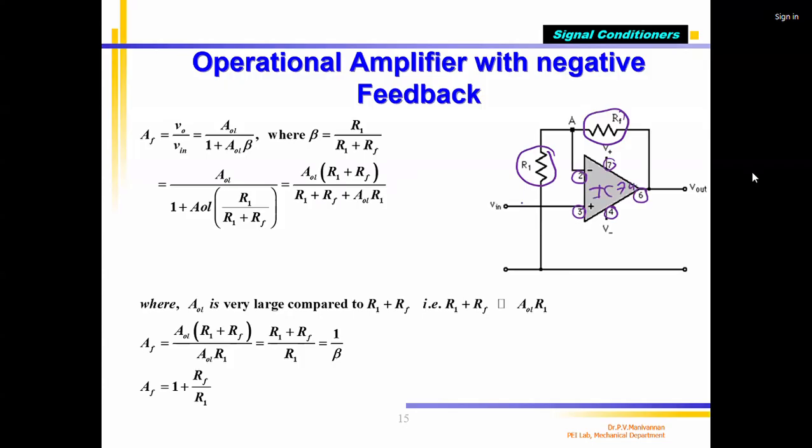But in case of the operation amplifier with negative feedback, what is the use of this? Negative feedback eliminates the output voltage dependency on AOL of the op-amp. Note that down. Okay, that is my output voltage. We are going to see how it works.